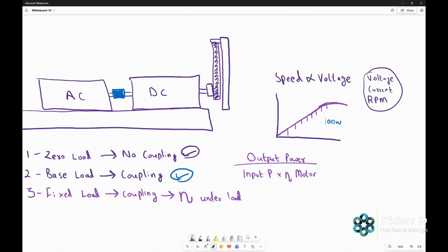And then we have to replicate the load based on how much load the generator applies onto the machine. When this generator is running, you have to see the X amount of load that it applies. Then we have to replicate this X amount of load onto the friction belt. This procedure has to be done once, as I said. So this procedure has already been done, and then we can look at the Excel sheet for the generator.